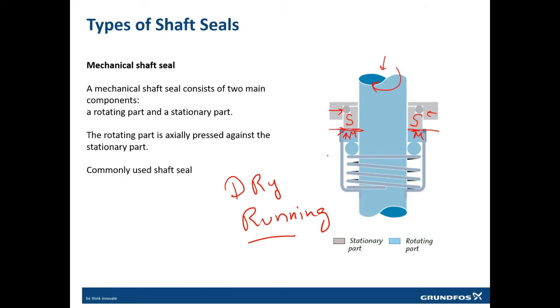So never ever run the pump without the water, because the water which you are pushing is also the media for cooling components such as the shaft seal of the pump. So this is the most important point you need to remember.